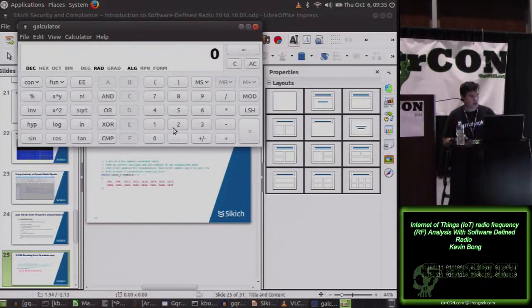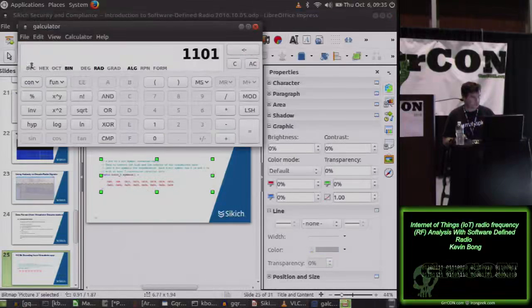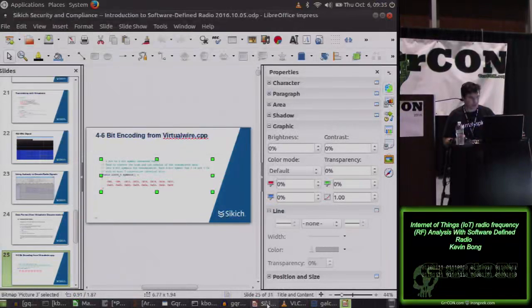Thank you very much. So if we just look at D, we're going to go to hex D and look at what that is in binary. In 6 bits it's 0, 0, 1, 1, 0, 1. So there's an equal number of zeros and ones. And if we go back and look at this slide, the next one is 0xe, I think. Again, we're going to see 0, 0, 1, 1, 1, 0. So in all 6 bits, you're going to have 3 zeros and 3 ones, but you've got to map these numbers back to those numbers.